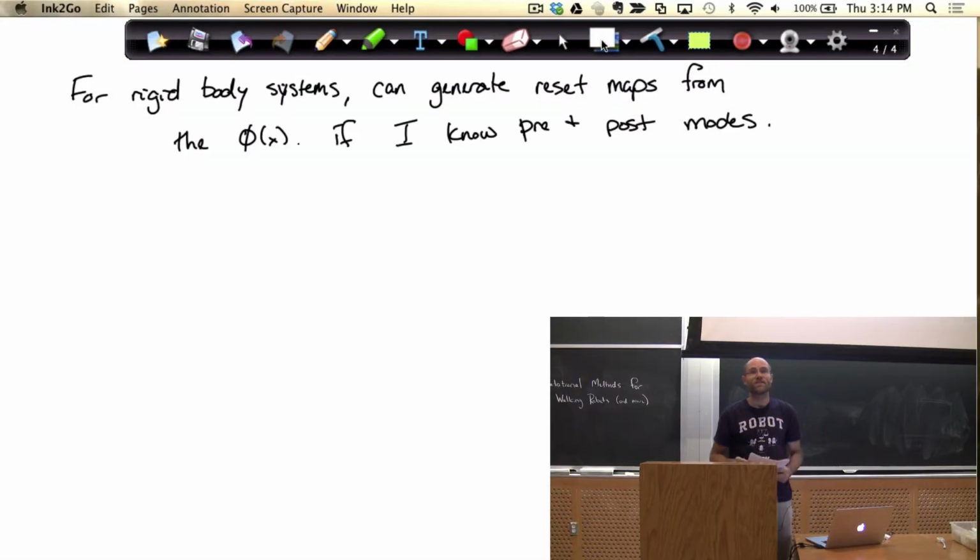Okay, any questions on that? Yeah. It seems in this Fast Runner model we also have closed kinematic chains. How can you approach such constraints from the framework? Awesome. Good question. So closed kinematic chains, you can actually write down the dynamics explicitly. So you don't have to enforce them in the numerics. You can actually write down your equations of motion for the constrained system and solve them away. If you chose to, you could also just list that as a constraint in the optimization, and it would solve that for you.